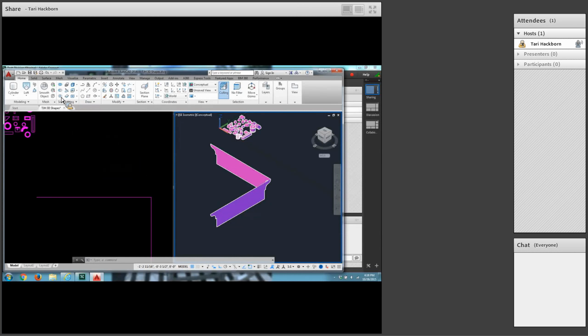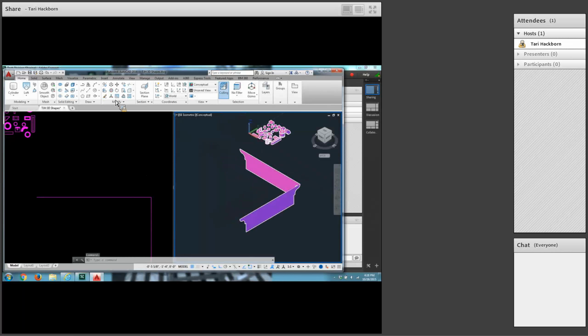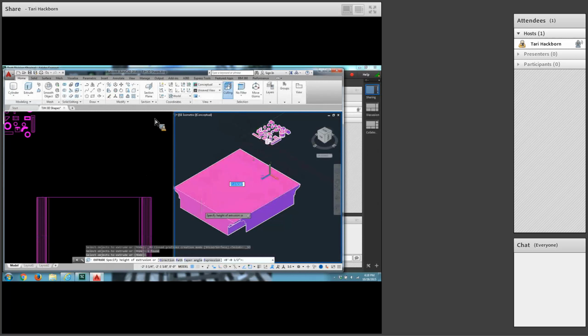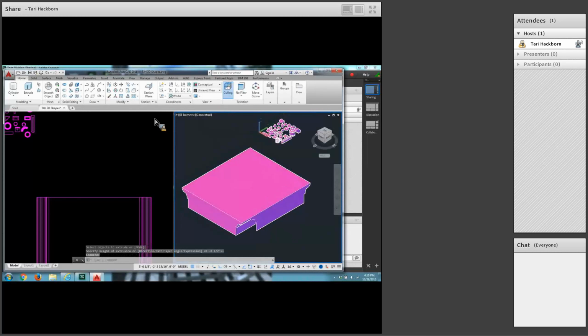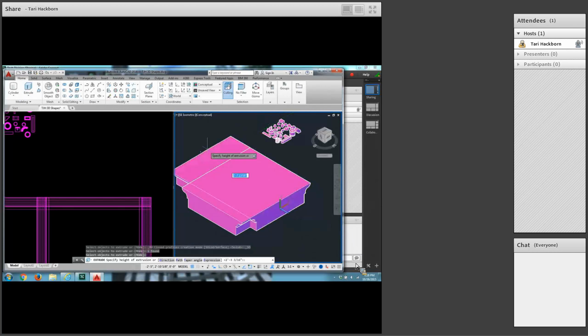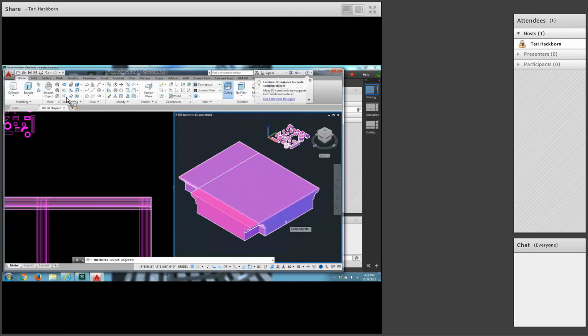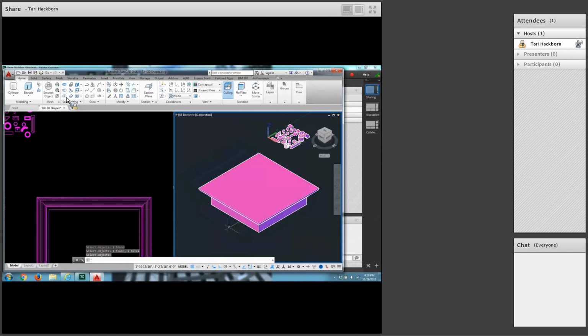Okay, so over here we have to extrude both of these. Let's find extrude up here. I'm going to extrude this one, click and enter, and I'm just going to pull it way far in this direction, farther than it has to go. Okay, I want to make sure I extrude it past that shape. And then I'm going to extrude the other one. Click it and enter and pull it past that. So they actually cross each other, don't they? Now intersect. Okay, right there. Select this one and press enter, and there it is.